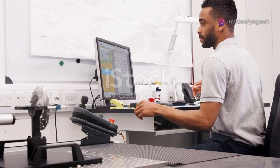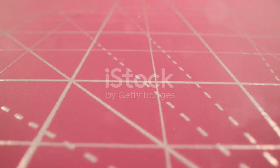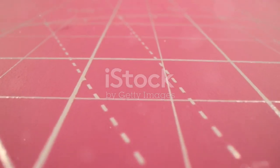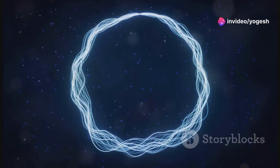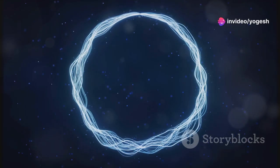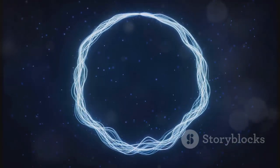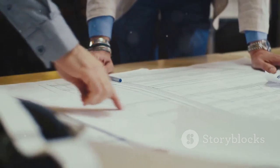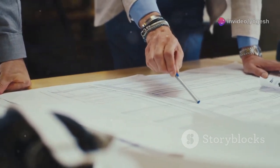Let's look closer at the coordinate table, the recipe for a spline. The table lists each point's X and Y coordinates, measured from a defined origin. This set of points is the blueprint for the curve. No guesswork. The number of points depends on the curve's complexity. Simple curves need a few. Complex ones might need hundreds. The goal is enough points for accuracy, but not so many that it's overwhelming.